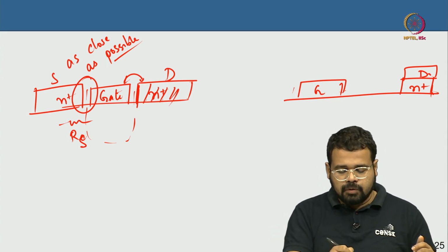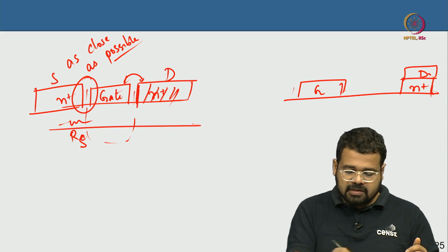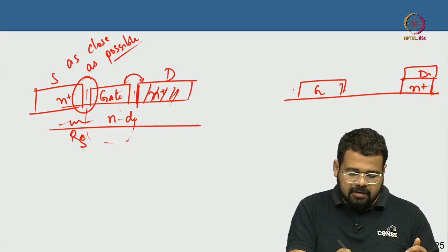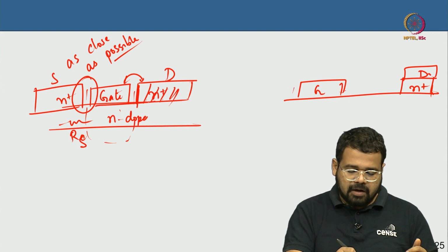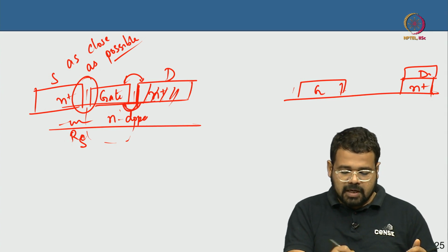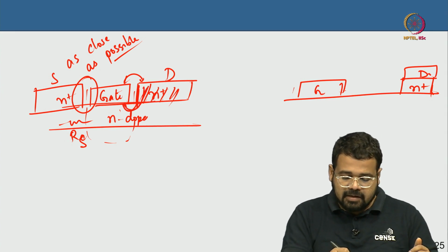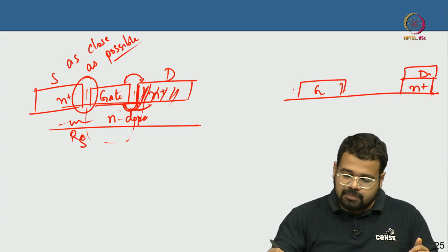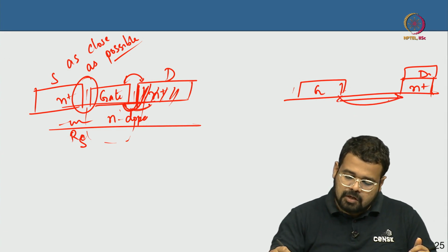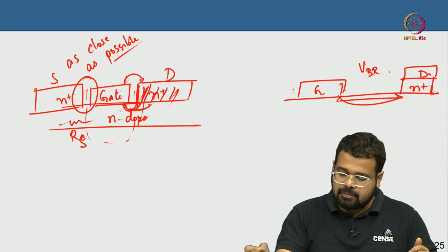So very close, you will break down sooner, and you have to remember that this is an active N doped layer here. Okay, it is an active N doped layer, and you are going to drop the field between the gate and the drain. So when you have a highly conducting layer here, you are not going to drop the field as much, but here you are going to have a larger spacing, so your breakdown voltage will improve here.